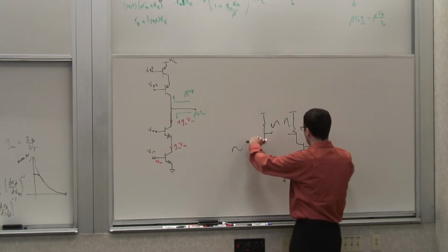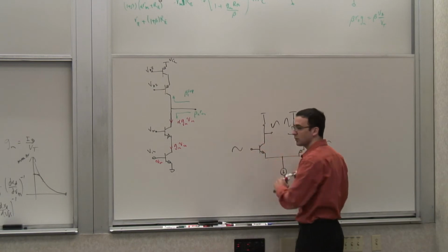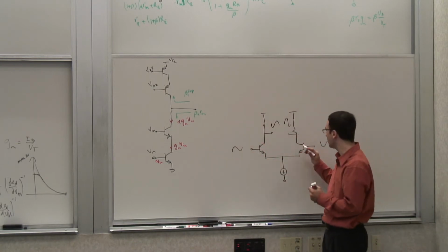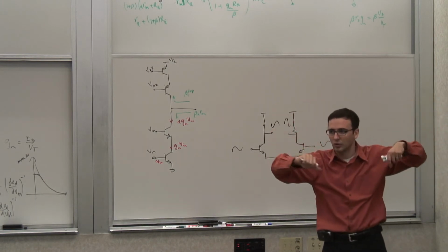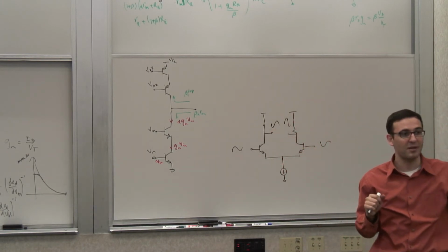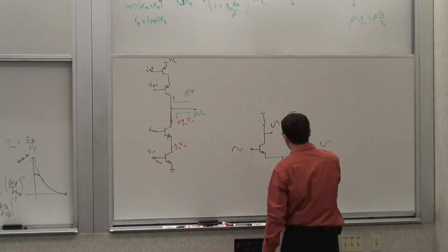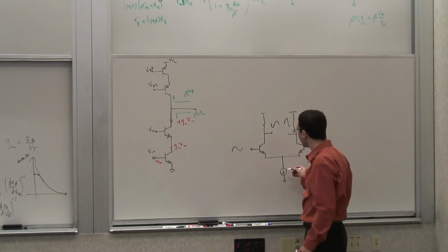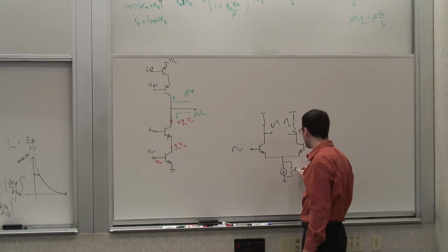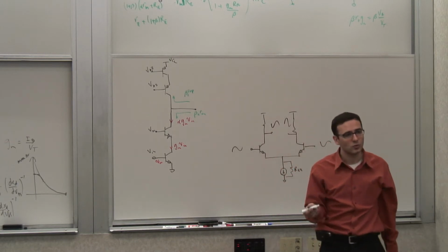So in this case, if I apply a common mode voltage, this node follows that node, but these guys will not move at all. Of course, up to a certain point, until the transistor enters saturation. If I raise it so much, the transistor can go into saturation. But for as long as I remain in the forward active region, for the simplified model, if I don't worry about the RO and the output resistance of this guy, it doesn't move at all. But practically, of course, I have some resistance associated with this, and I have some output resistance here, but nonetheless, it still works quite well.